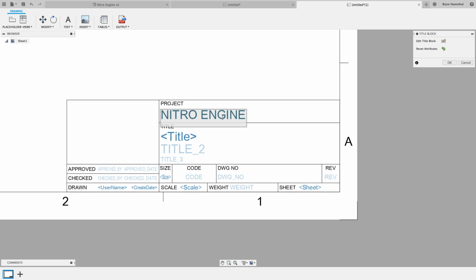So you'll notice that the blue words here are all editable. So I can double check, change anything. I could go through here, change that to my Aaron's name. If I could spell his name right, you could see these are the edited ones. This is important to know because I'll show you in a second as we're creating title blocks. So these are called attributes, and then these dark black words I can't do anything of.